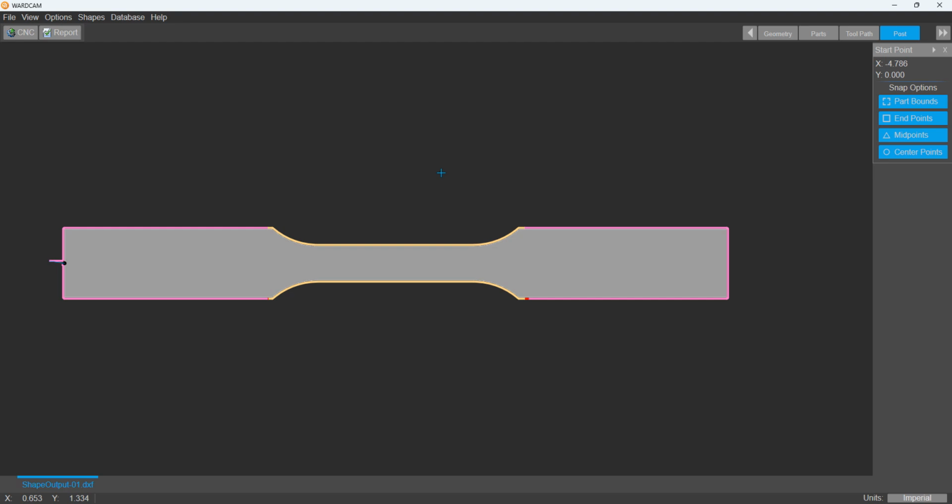And then when you do go to cut this on the machine, obviously a good idea to not have the tube in the machine and dry run this at a safe height so you don't break anything. And if you have any questions on that, let me know. Thanks.